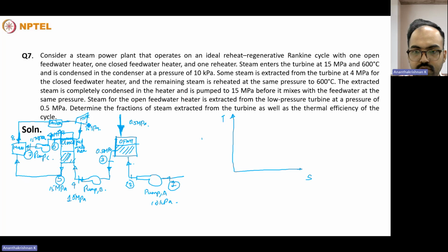So this can be quite confusing. So I'll draw a boiler 2 separately, and then it comes out of it. And I forgot to add a few state points. So 8, it will be 9, high pressure turbine, the exit of the high pressure turbine, that will be at 11. That will be bled to the closed feed water heater. And then the exit of the high pressure turbine will be 12, and the boiler heating.